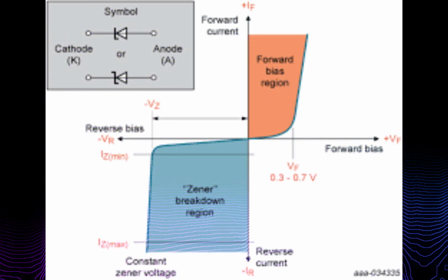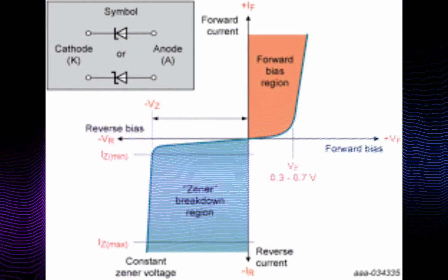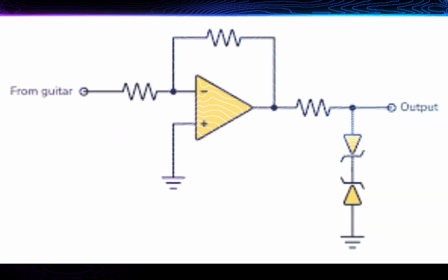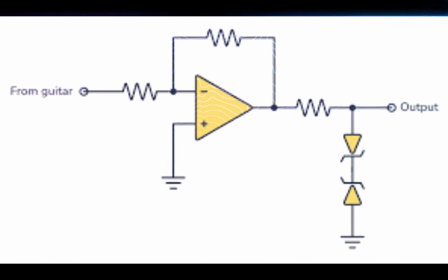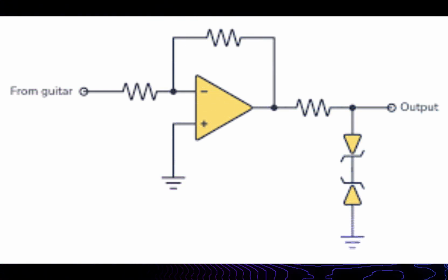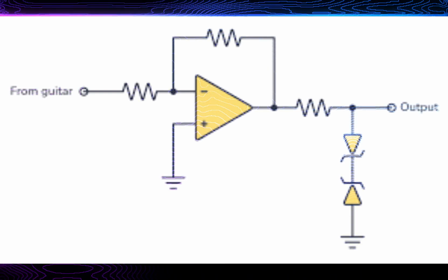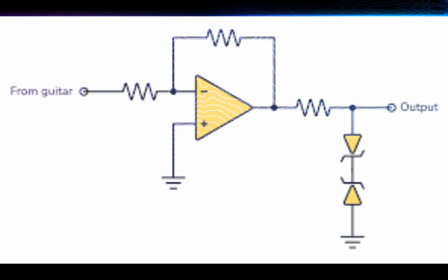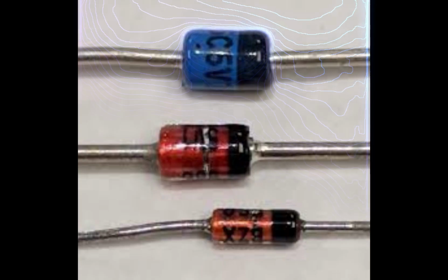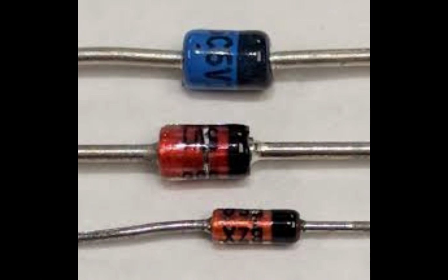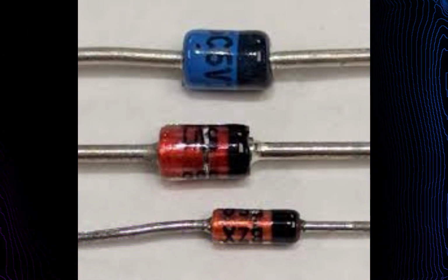Voltage regulator. When the load voltage equals the Zener voltage of a diode, the series connected resistors limit the current through the diode. This serves to regulate voltage when there is an excess amount of voltage while the diode is conducting. The diode generates noise. This can be suppressed by adding a large value decoupling capacitor across the diode.